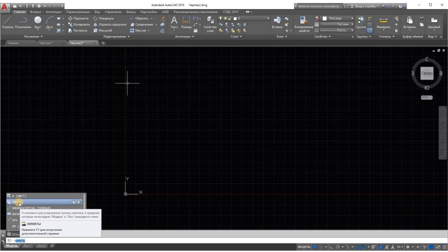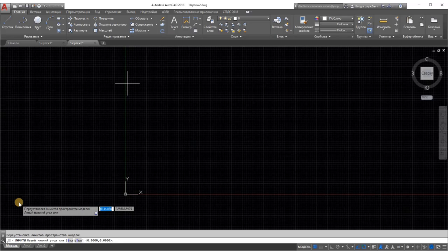You currently have a new blank file, but it's a little difficult to tell the size of your drawing area. Let's set up the work area so that you have a better idea of the space with which you're working. First, enter Limits.